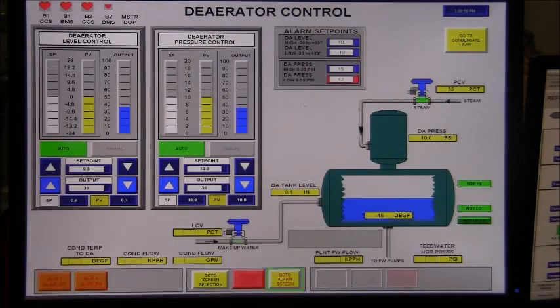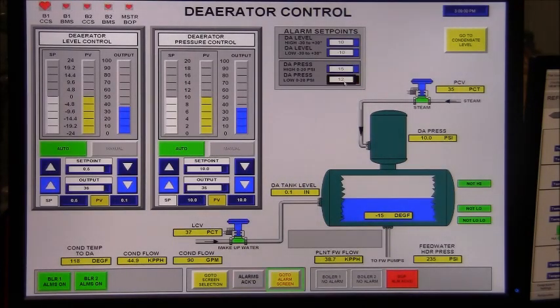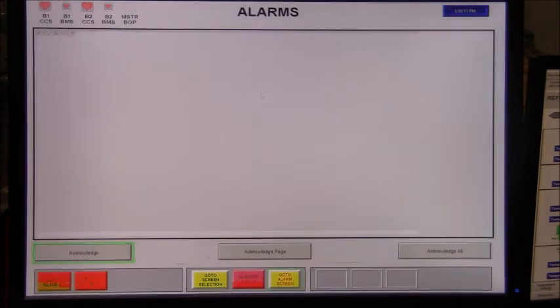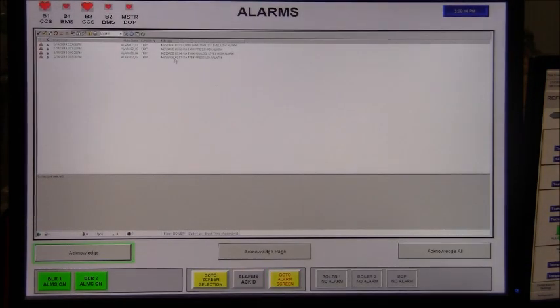Go back to the DA, I'm going to set the low alarm, and that's still flashing because it's still in the alarm state. I'm going to set the low alarm back to 5 psi. That should extinguish and the alarm will be...